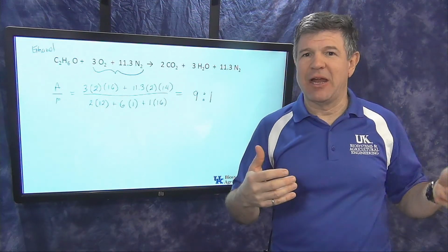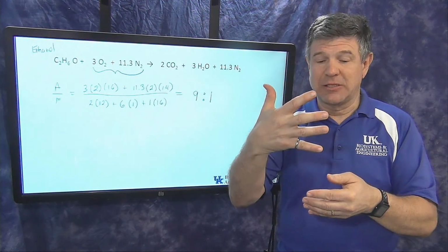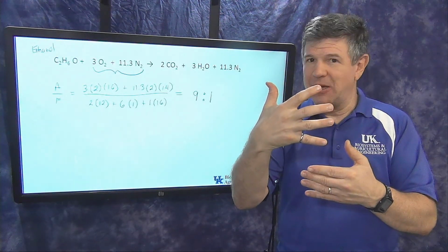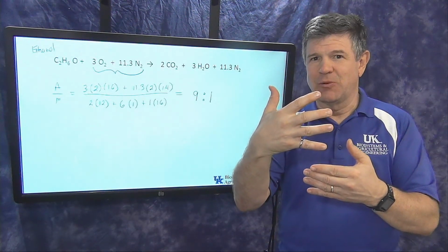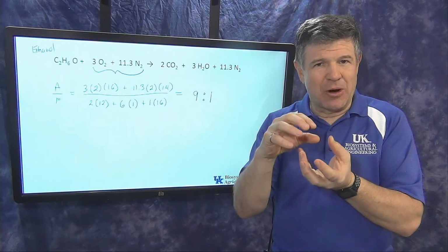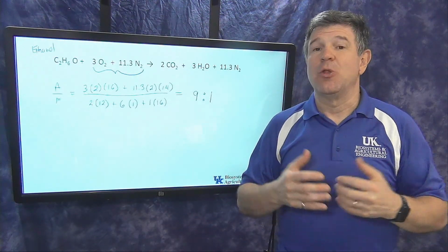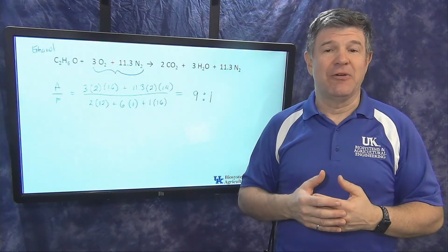If I take straight ethanol and put it into that engine, it's not going to run well because I've got way too much air. It's set up for all this air in there. So to run ethanol, I would have to retune that carburetor so that there's not as much air going through, so it's going to burn better. So that's what's going on inside of our vehicle.